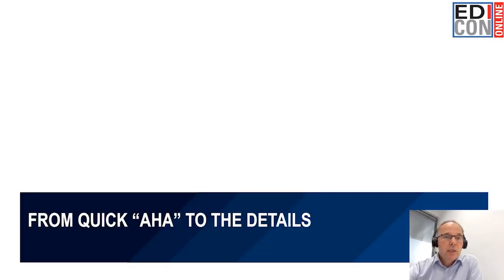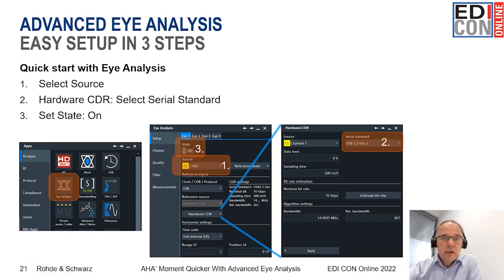So how does it then look on the machine itself, on the oscilloscope? I select under my application tools the eye diagram. I configure my hardware CDR. So in the easiest way, I just define what standard I use, and then I just switch on, and I get my eye diagram. So just 3 simple steps in order to get to an eye diagram.